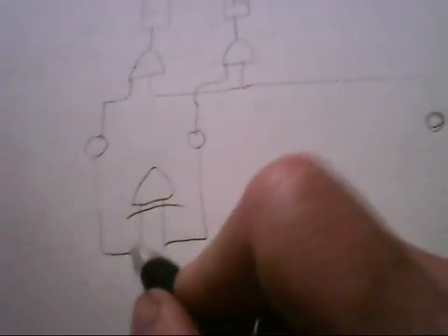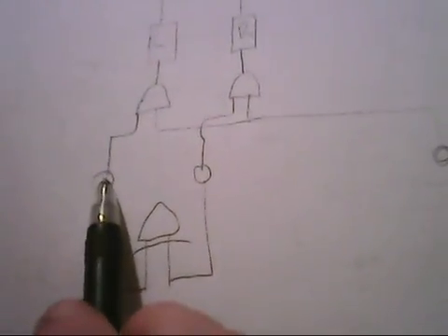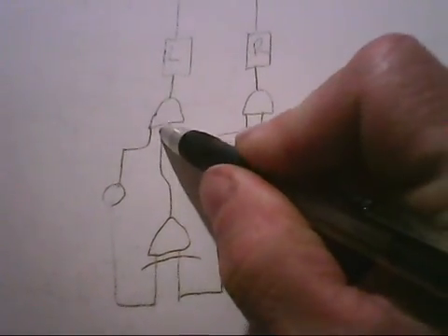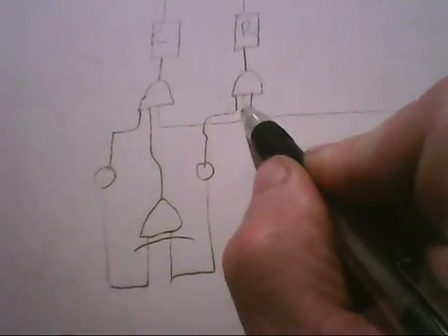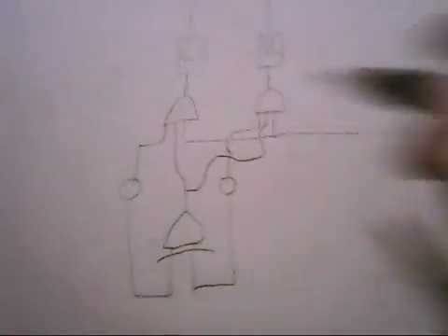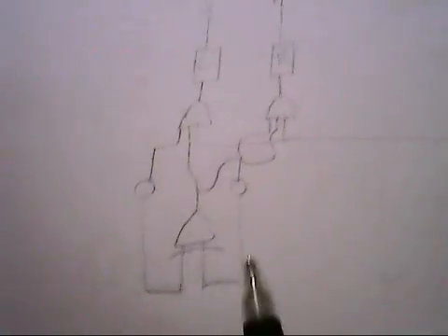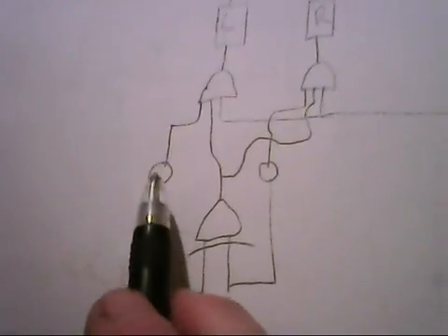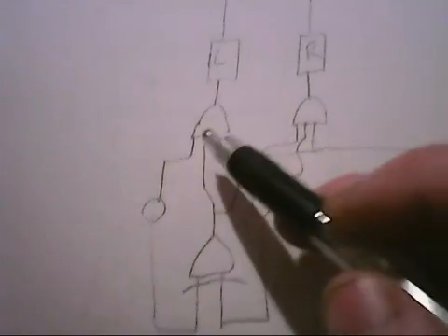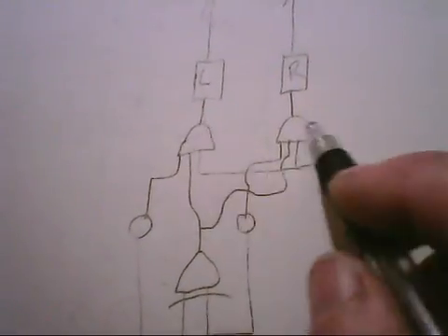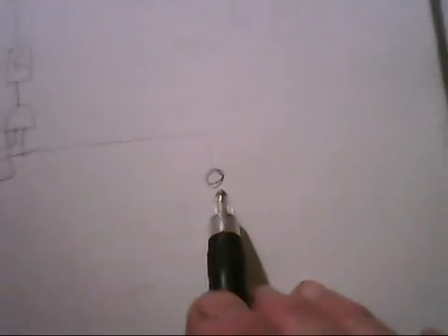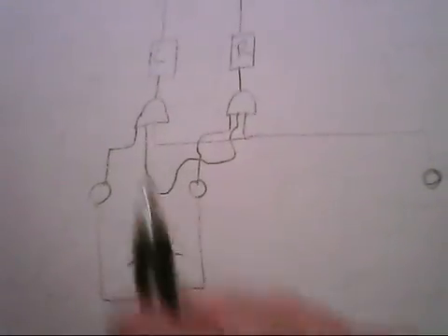what would happen then is when this button goes high here, it goes high here, and the output will fan out into both of these. So when there's an input on one switch, there's an input going through the exclusive OR gate, and there's an output that goes to an input of both AND gates, and then the thing that determines which AND gate comes on would be the firing button, because that would give you the third input.